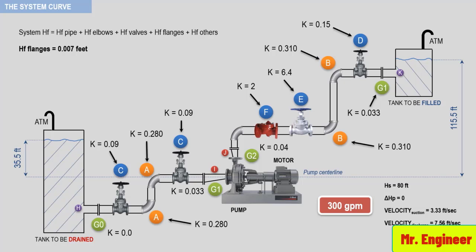This is clearly an insignificant number. With only one pump and less than 200 feet of pipe in our system, there are only 4 flanges. But think of it this way. Imagine an oil refinery with 20,000 pumps and thousands of miles of pipe and equipment on site. Imagine the number of flanges in this case. Imagine also the number of flanges in the firewater system in a skyscraper building. In a real set of circumstances, the friction head values through flanges could be significant, and they would have to be calculated to specify the correct pumps.